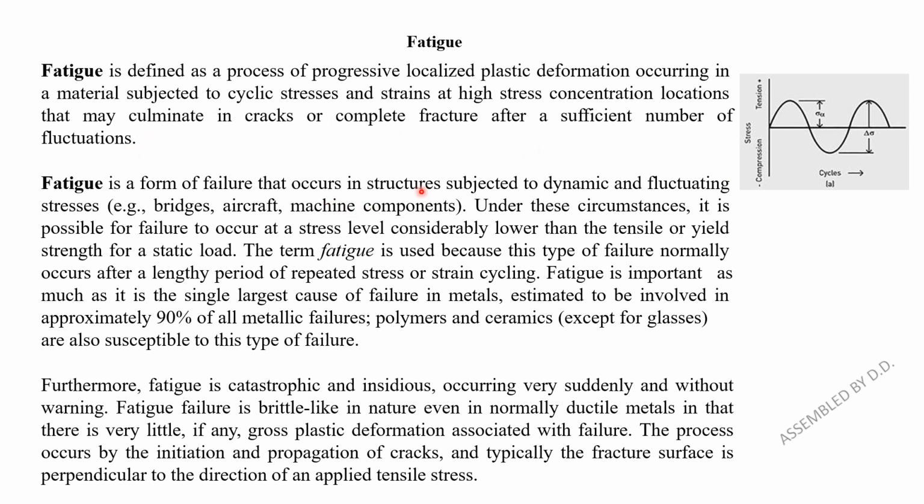Fatigue is a form of failure that occurs in structures subjected to dynamic and fluctuating stresses, for example, bridges, aircraft, machine components, etc. Under these circumstances, it is possible for failure to occur at a stress level considerably lower than the tensile or yield strength for a static load. The term fatigue is used because this type of failure normally occurs after a lengthy period of repeated stress or strain cycling.